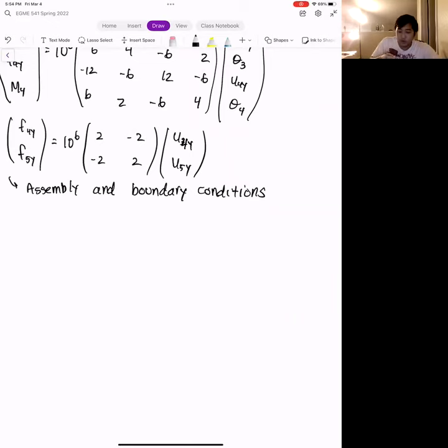But before we do that, we have to make space for everything. For this system, since we have 4 nodes that have beam deformations and 1 node that has a spring deformation, we're going to have 9 degrees of freedom overall, so a 9 by 9 matrix. We have F1y, M1, F2y, M2, F3y, M3, F4y, M4, and F5y.